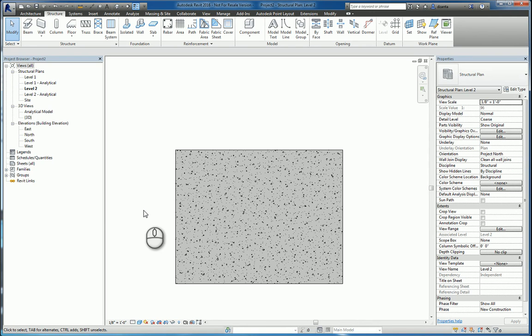In today's screencast, we'll be taking a look at Revit 2016 and the area and path reinforcement commands. Here I have a structural floor slab. If I need to put in area or path reinforcing, I can select either command. So I'll start with area. The lower left corner of your Revit screen, the command line, will tell you to pick the structural floor or wall for the area reinforcement.